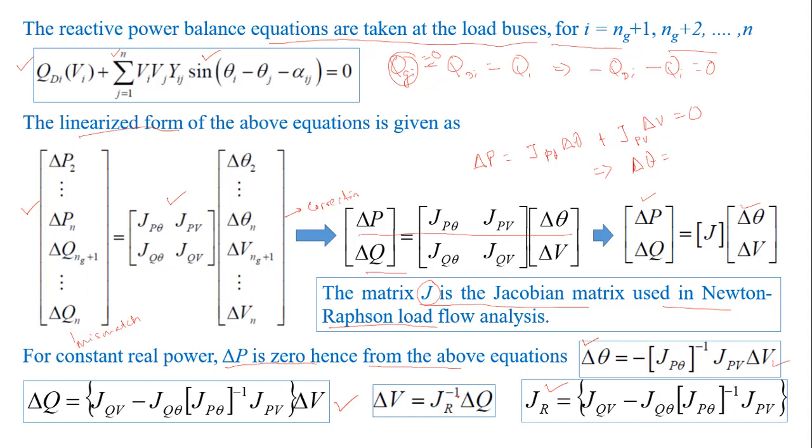If I take the inverse of JR, this will give me the sensitivity of voltage, the change in voltage with respect to change in reactive power injection.